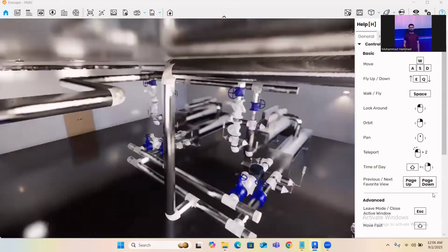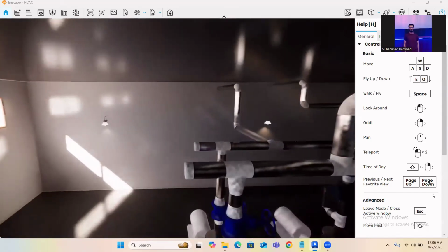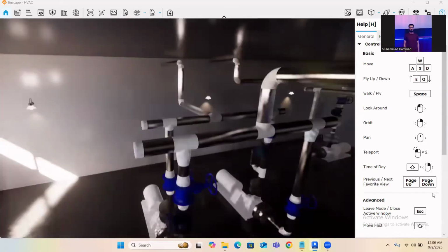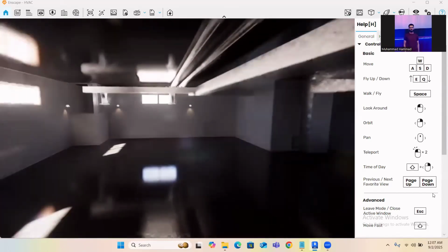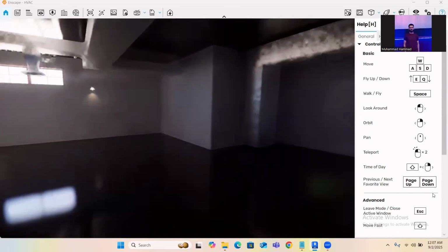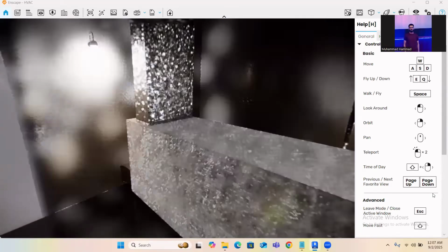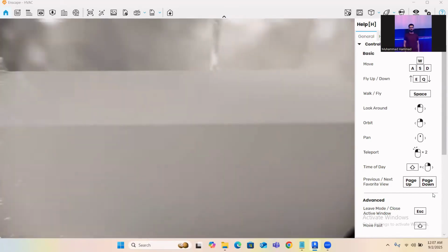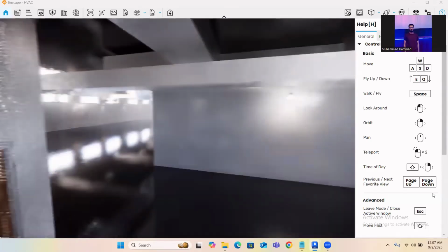So on the condenser side, the pipe is going towards the cooling tower, and at the evaporator side, these secondary pumps are used to transfer the chilled water towards the air handling unit. And there I have got this air handling unit at the basement, one serving each floor. So you can see this AHU, and then this is the space that this AHU is serving.